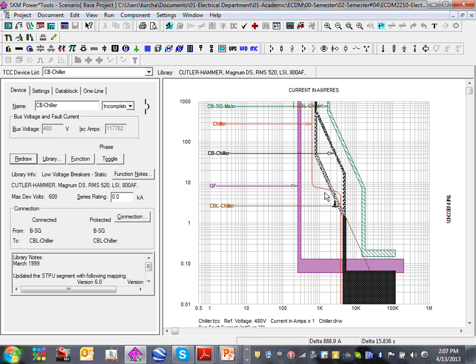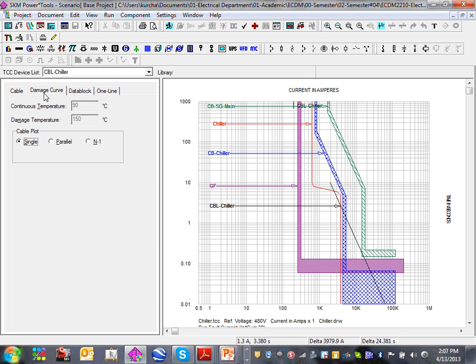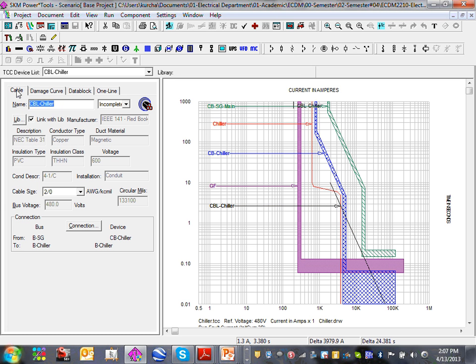So you might have to lower it, but you have an issue because I don't know what size conductor we're using here. I'm using 2/0 cable. At 2/0, based on this, it will burn right here, or it will be damaged. That was grossly undersized.